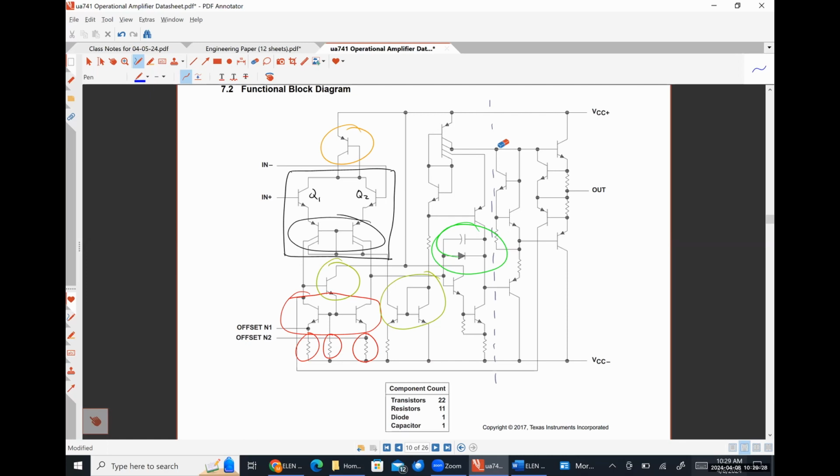Because if we had a single-ended input, we could only do stuff to one signal, which means our options are limited to making it larger or making it smaller. End of story. As we can accommodate more than one input, we can do much more mathematical manipulation of those signals. So a consequence of a differential pair is that noise reduction occurs if we apply the noise equally to both inputs. But the true purpose of a differential pair is to be able to manipulate multiple input signals.